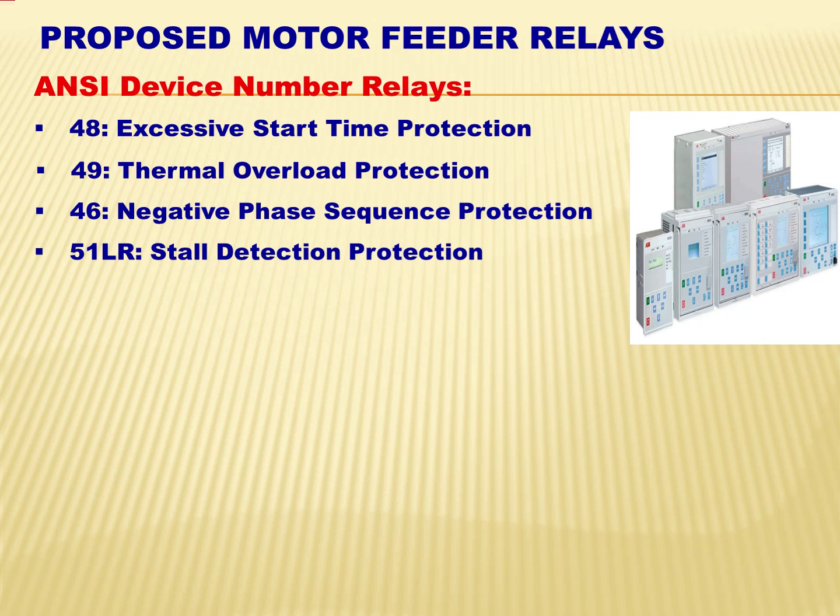Stalling is determined by checking that the current is at or near its stalling value, and the tripping time is between the cold and hot thermal times for this current. To protect the motor from this kind of abnormality, we require a stall detection relay or relay 51LR.